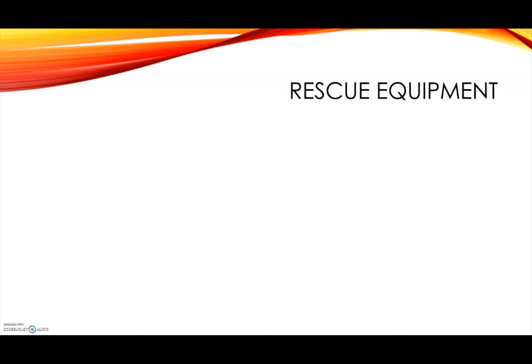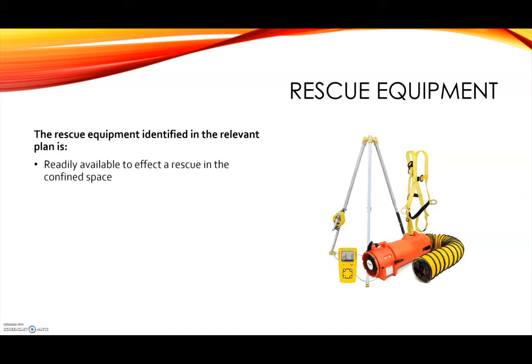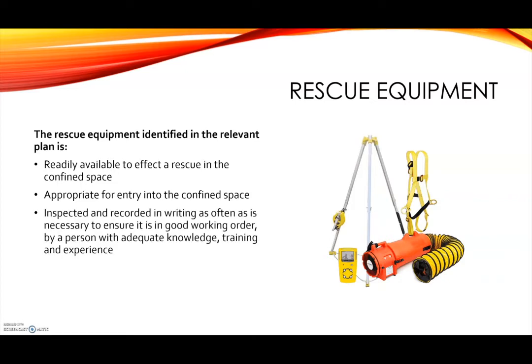Rescue equipment. The rescue equipment identified in the relevant plan is readily available to effect a rescue in the confined space, appropriate for entry into the confined space, inspected and recorded in writing as often as is necessary to ensure it is in good working order by a person with adequate knowledge, training, and experience.